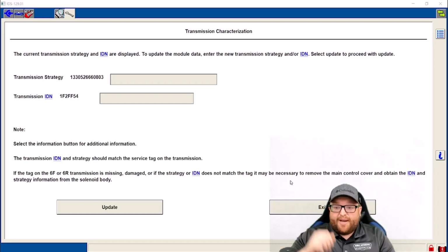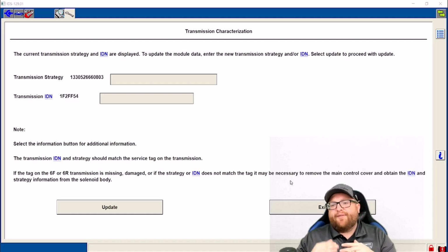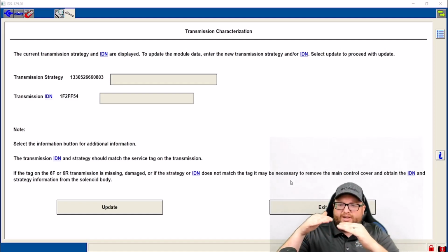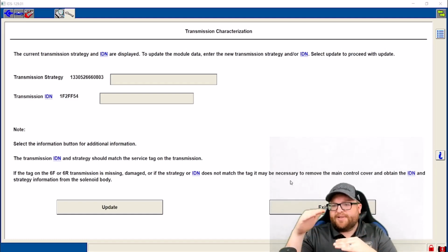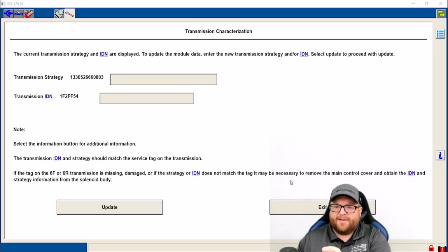So I believe is what happens, and you've got to watch with these push button Fords because they're really bad about doing it. Even though the voltage is at 12 volts, they want to drop and go into like a power conservation mode, right? So it senses that you've not started the vehicle and you're just sitting there, so it kind of starts shutting things down to conserve power. And usually it'll say something on the dash like battery something relay. I forgot what they called it, but I think that's what happened in this scenario.